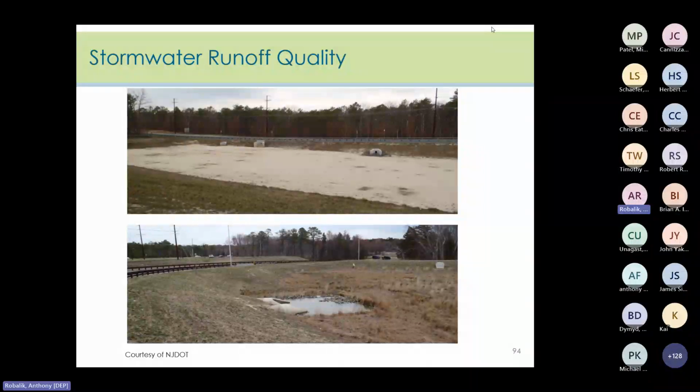So here's an example of 2 infiltration basins. The top one is functioning correctly. As you can see, the bottom one has ponding at the inlet locations, and there's a lot of vegetation established. And this is a pretty big basin, so something to consider is, if there's vegetation, how will compaction from the vegetative maintenance impact the ability of the basin to infiltrate? Additionally, the vegetation that is breaking down in standing water forms a biofilm that can cover the sand layer and greatly reduce the basin's ability to infiltrate. And this is why the BMP manual does not allow for vegetated bottoms for an infiltration basin.